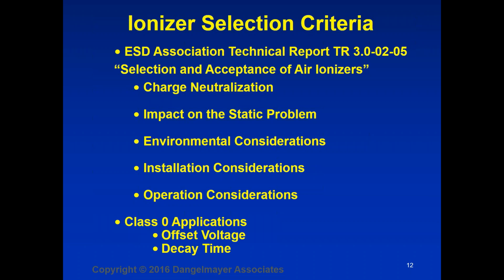The bottom line here is that if the ionizer is not doing something for you that you can actually measure, there's really no reason to be using it. There are other methods of counteracting static charge generation, and they should be tried first. But if you actually have a static problem and you suspect that ionizers will solve that problem, what the standard directs you to do is to make some measurements to see whether that's actually happening. And there are some suggestions in the document of methods to do that.